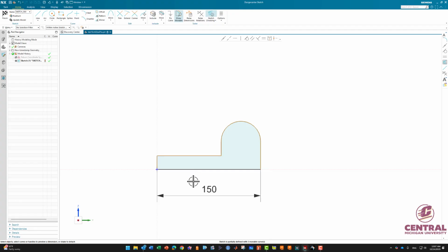And next time we're going to learn about geometrical constraints or sketch constraints to make this sketch more intelligent and more robust. For now, just add more dimensions as you need. So if I keep going, based on the book, I need this one. Click and say 40, enter. Then you can see it will turn black. This line becomes black, so it's been confirmed. This one also, click. Needs to be 20. Enter. Click. There we go.